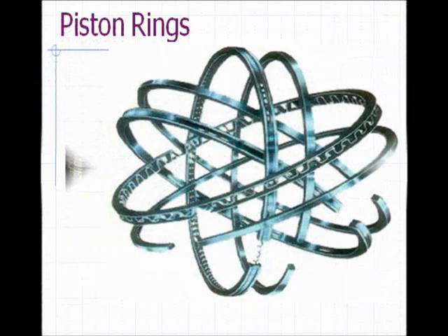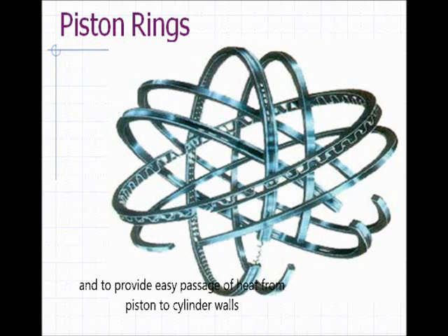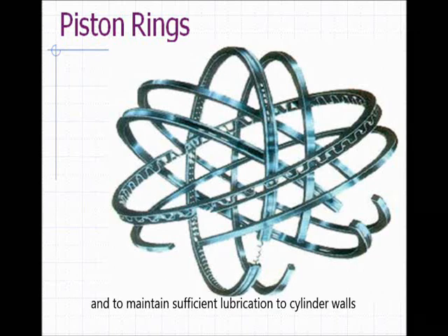Then the next part is the piston rings. The main function of the piston rings is to form a seal, to provide easy passage of heat from the piston to the cylinder walls, and to maintain sufficient lubrication to the cylinder walls.